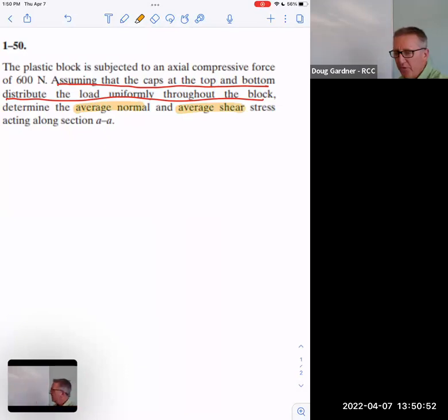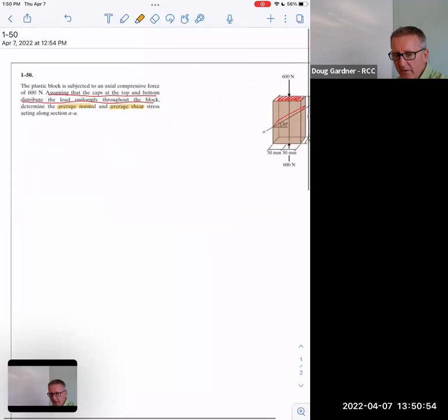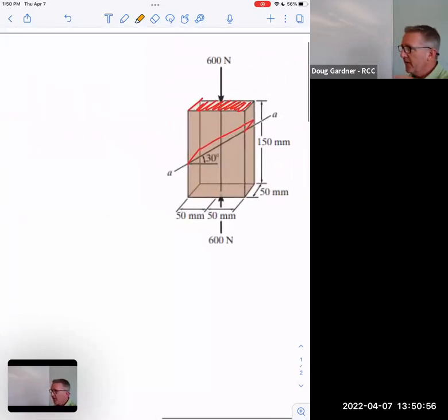And by the way, that's how you label sections. You're going to need to start thinking about how you label stuff. When I draw house plans, I draw a section through the house all the time and show staircases and stuff. So it's really nice if on the floor plan I draw a line that says this is section AA, and then they can look over and see the side view of it.